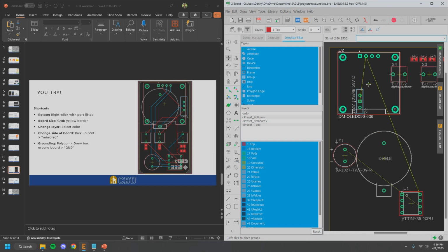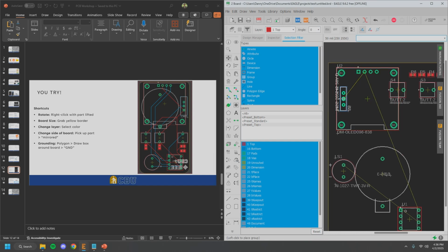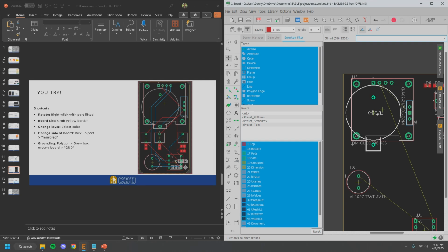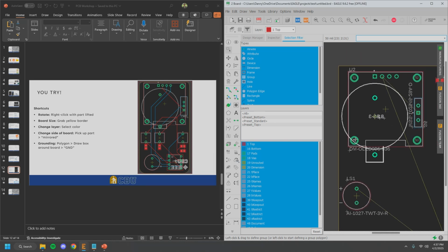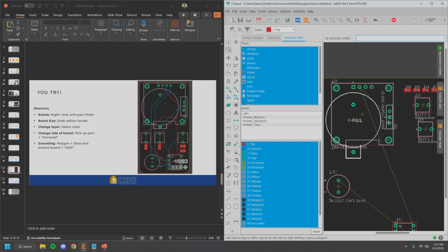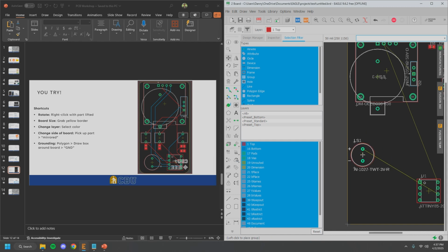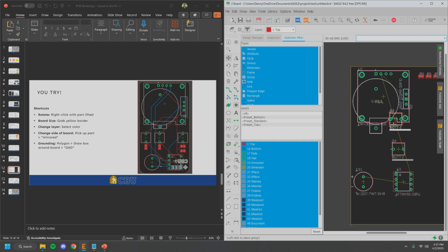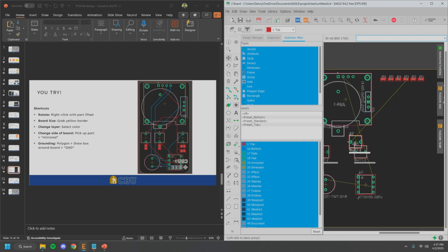So what we're going to want to do is move our screen there, our switch to this side, slot in our board here, or our power supply here, so that it's not overlapping anything. These are just screw holes, so it does not matter if you actually put them over there. And you can see it's already starting to take form here. You're going to want to move the speaker down, the AT tiny here, move our buttons, and then some of our resistors.